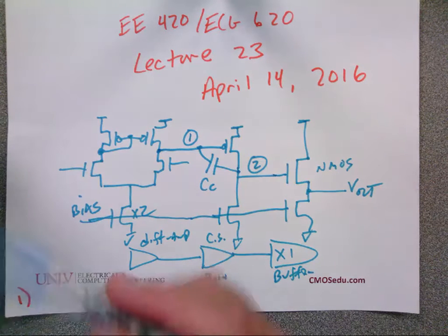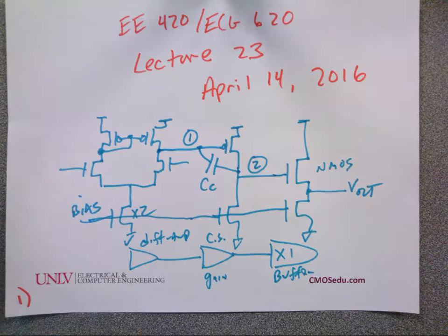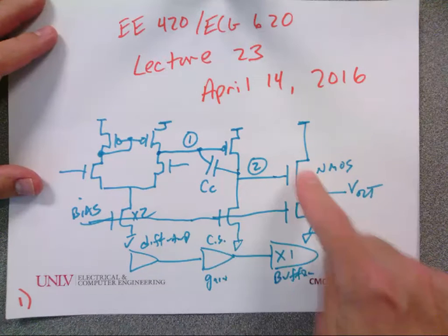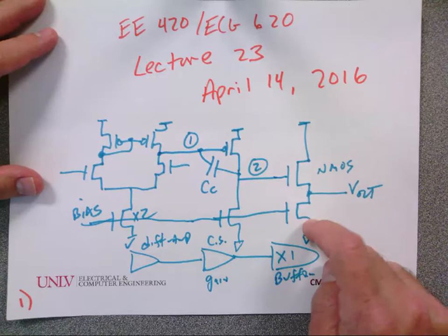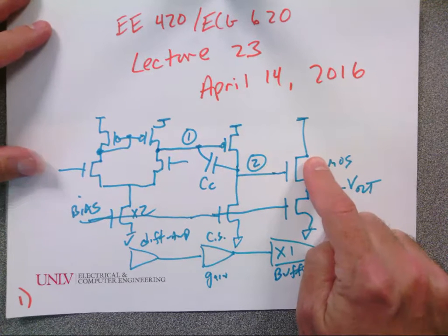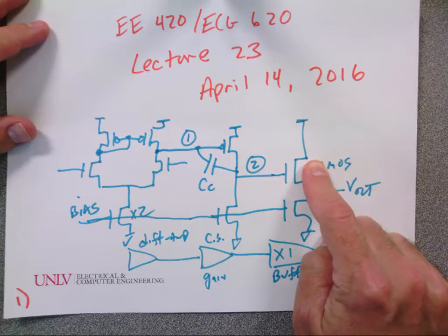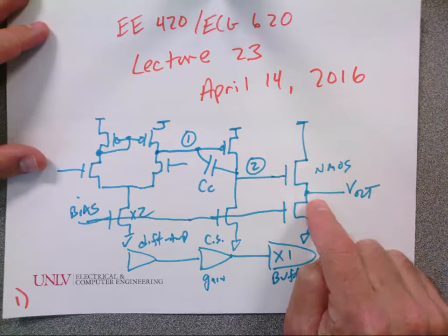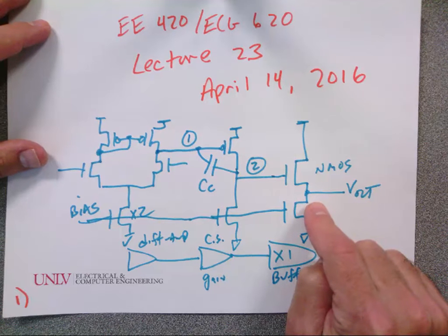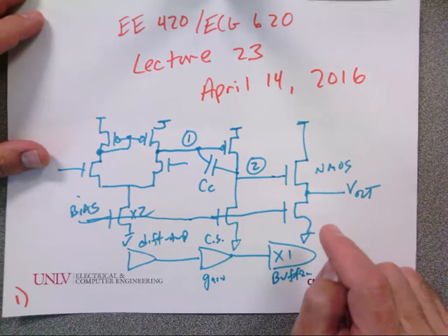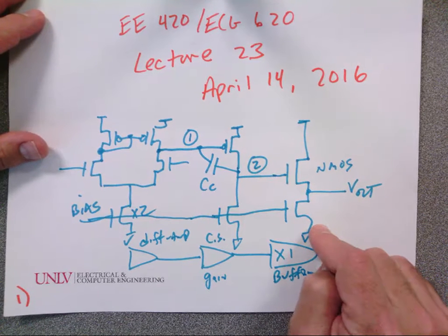Question? Just curious for the actual. You know, you probably answered what you're saying. So all right. So, I don't know how to select C sub C. I don't know how to select the sizes here. So I'm going to use the values from table 9.1 as a starting point. Now notice, you're not doing your project using the 1 micron process. You're doing it using the C5 process. Okay? So you have to go through and get the VGSs and all that other stuff.